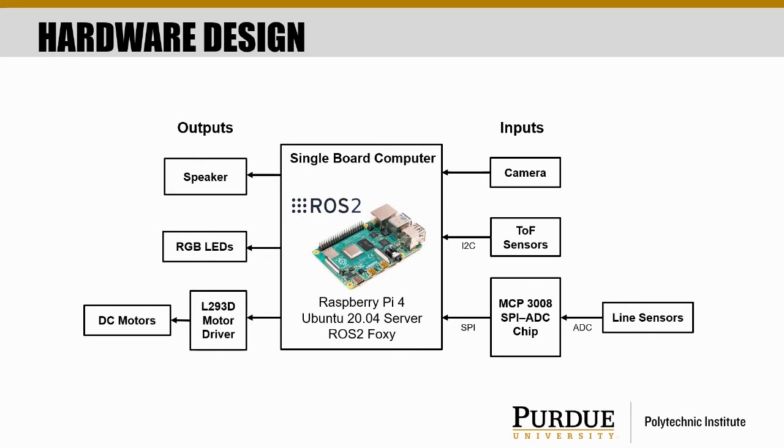The main processor, Raspberry Pi 4, utilizes ROS2 to control its input and output devices, as well as to receive commands from the main computer. Using ROS2 gives this platform huge flexibility by using nodes and topics. The nodes used for our robots could be divided into subscribers and publishers. Subscribers such as LED and motor nodes accept the values from the main computer and perform desired outputs, while publishers such as distance sensor and optic sensor nodes provide the collected data to the main computer.